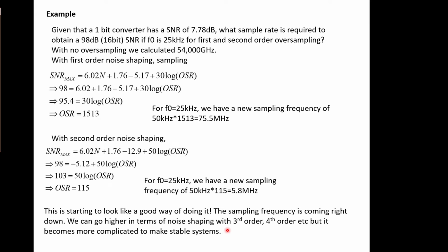But just be aware that this opens up a whole new ballgame of complicated systems that you can look into for this simple idea of single bit quantization and oversampling. So you can start to see the attractions of this, certainly from digital systems design anyway, because it's just delay gates and high frequency clocks, which is all good.